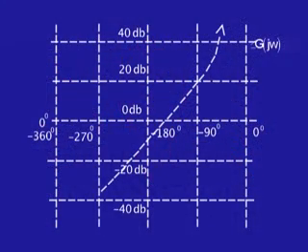So, for the same closed loop gain to be a constant, the set of all those points on this chart or on this plot will be a set of curves, one for each value of the constant. These curves are no longer circles. They look like ellipses, but they are not quite ellipses, and they are fairly complicated. However, Nichols went ahead and plotted a number of these curves, and subsequently the charts containing these curves were obtainable commercially.